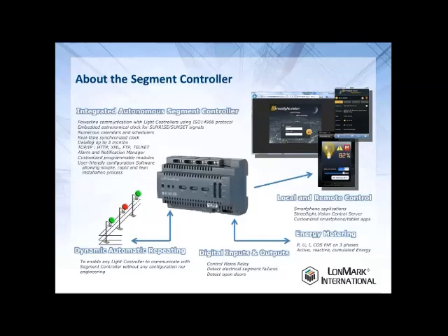On the power line communication, it also provides dynamic automatic repeating to make sure that even if the cabinet cannot communicate directly with a light point, which is pretty far away from the cabinet, the communication will be repeated by any light point controller on the network to avoid end customers or installers being obliged to install relays, repeaters, filters, or whatever you want.